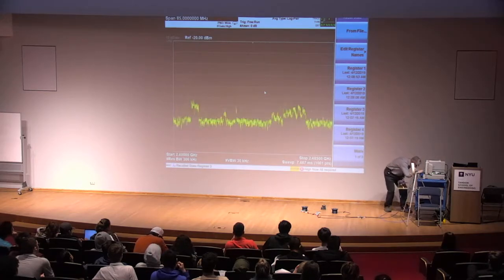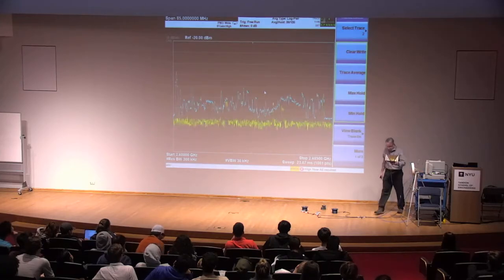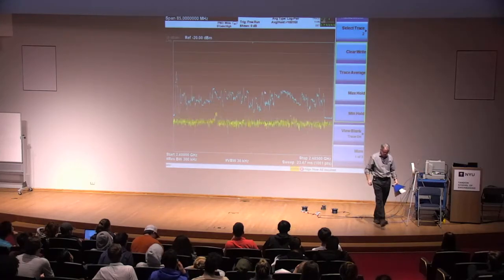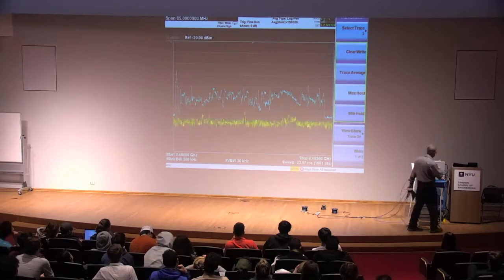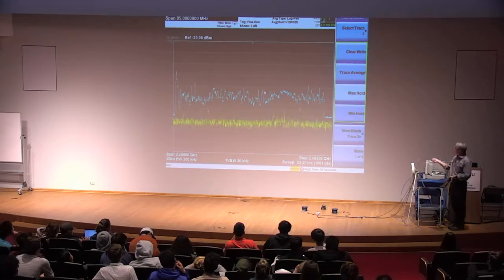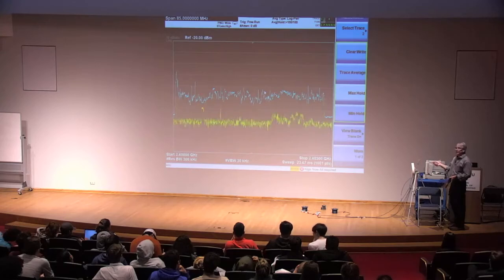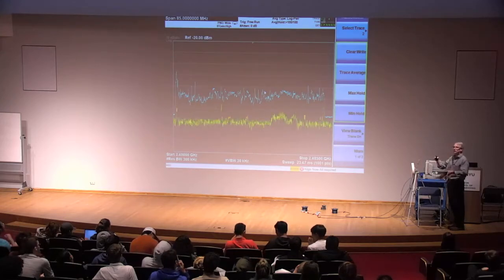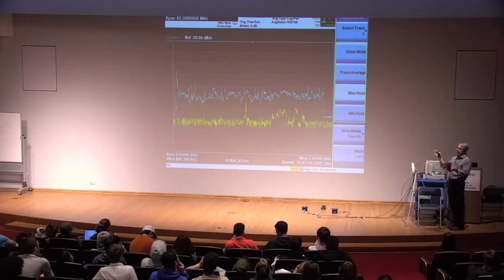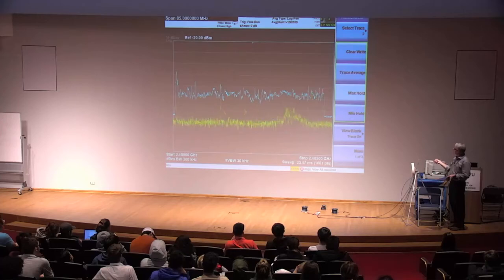Let me try one thing. See if we can sort of detect the maximums. To see if we can start to identify, over a period of time now, capturing all the maximum amplitudes. And there's a lot of activity here. You can see there's sort of this big blob here. There's another one here. This is the Wi-Fi. When you send out energy, you're sending out a lot of frequencies at once. But you don't do it for very long. So that's this.